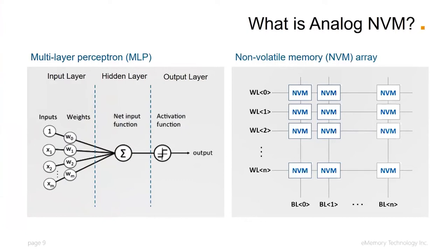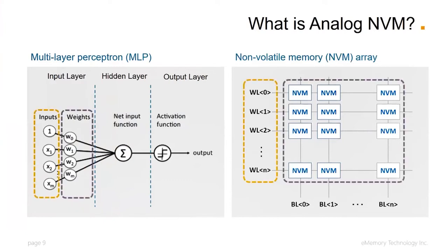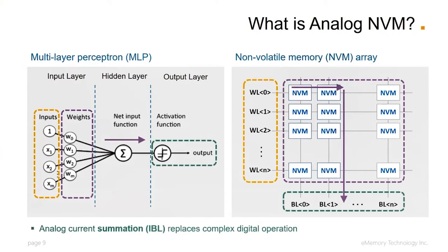We can see the data input is one data input. Weighting is the multi-memory unit. And the summation process is the multiply accumulate process. In this way, we call it MAC. It is the parallel computing operation to increase operating ability. The final step is to read out the analog current to identify what the output data is.